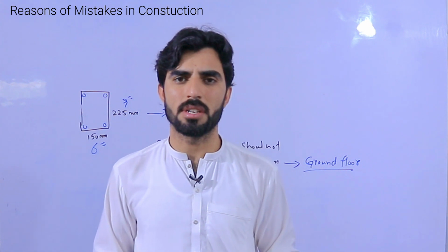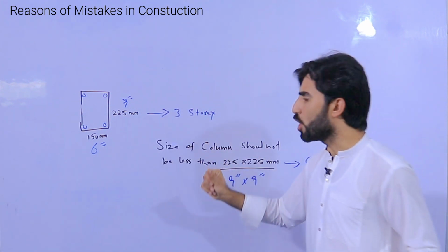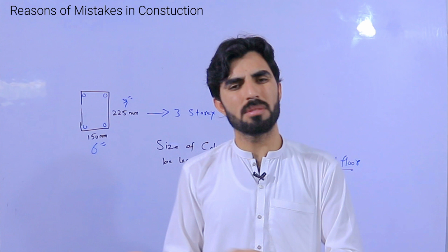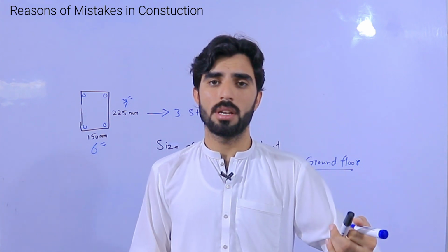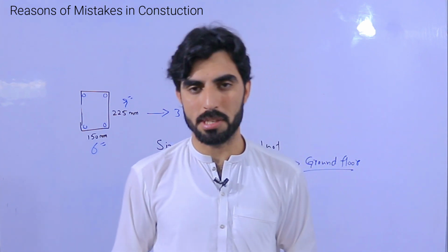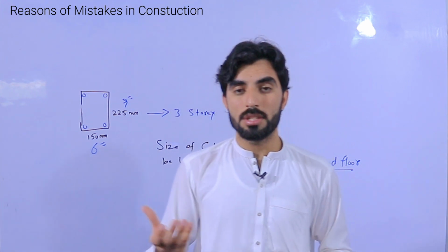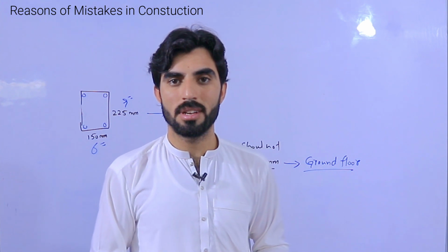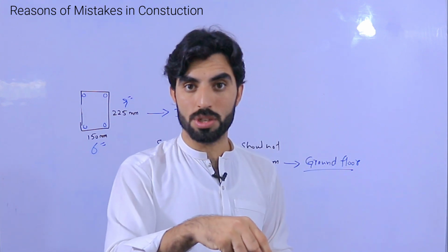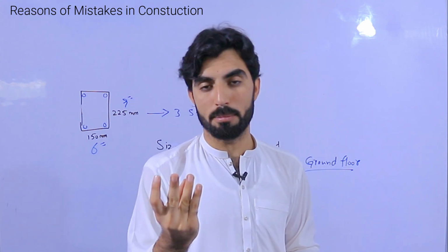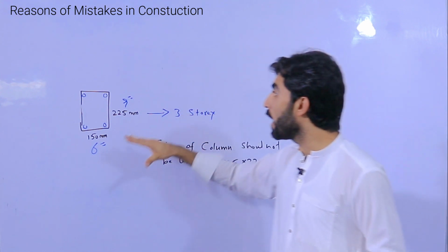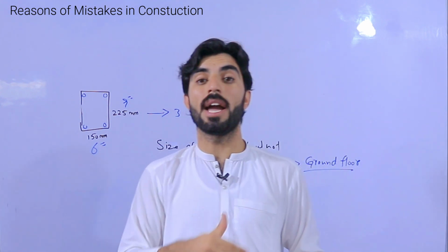It is not just architecture designing. You know, in many projects, they don't know what the depth of the foundation should be. Especially on the ground level, they construct a beam along with the column. So guys, this is impossible. It cannot support the structure load. The structure load should be transferred to the foundation, because the foundation is the place which can support the structure load with the help of beam and column. Therefore, remember guys, these things should be done by a structural designer, by an engineer.